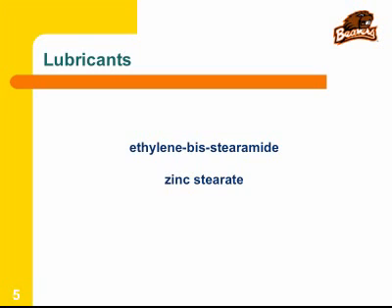There's another part of the molecule, in this case it's the zinc and the acid that is coordinated with that. In this case there are some nitrogen based compounds, and so they can interact with the surface of the powder and stick to the surface of the powder. So one part of the molecule sticks to the surface of the powder, the other part provides an oily coating to reduce wear, the friction between the two particles.